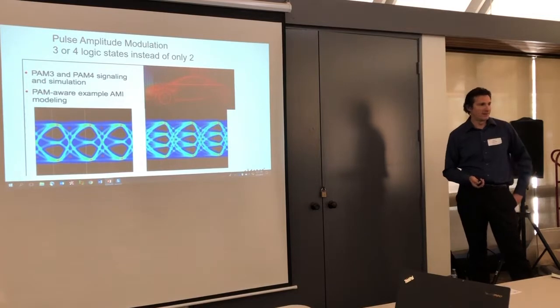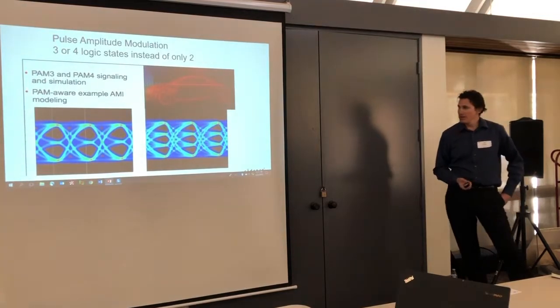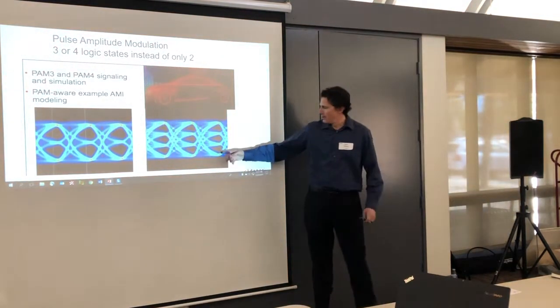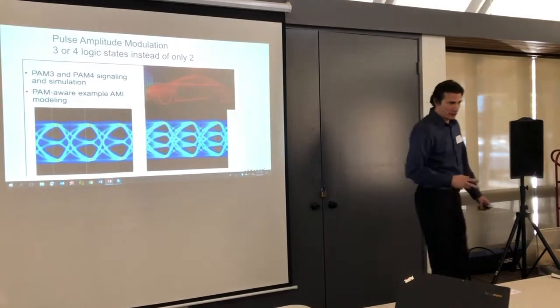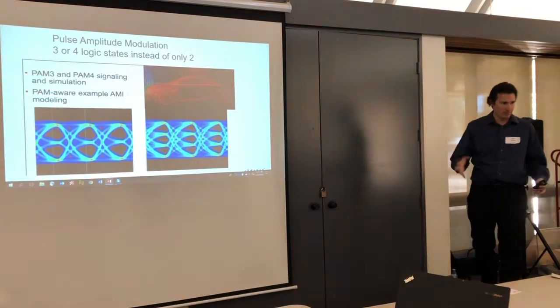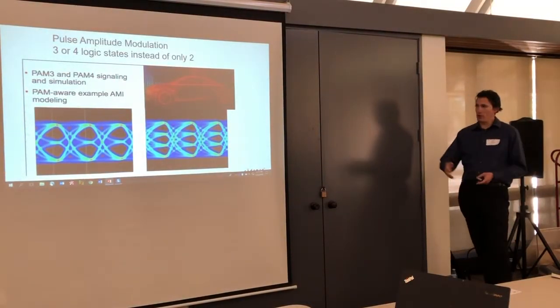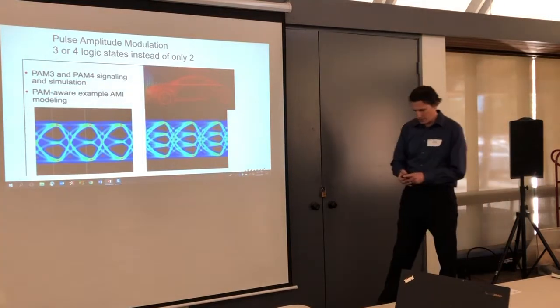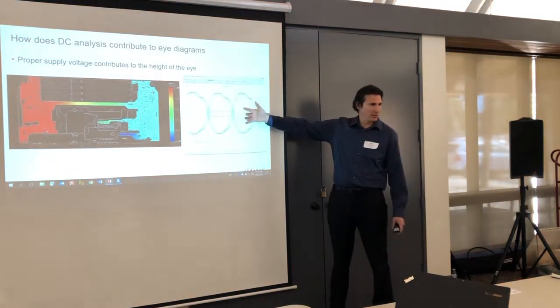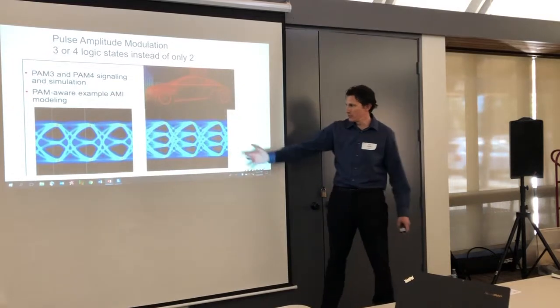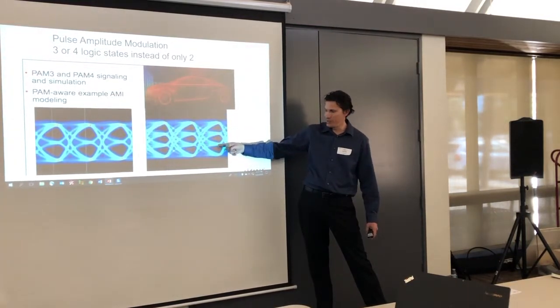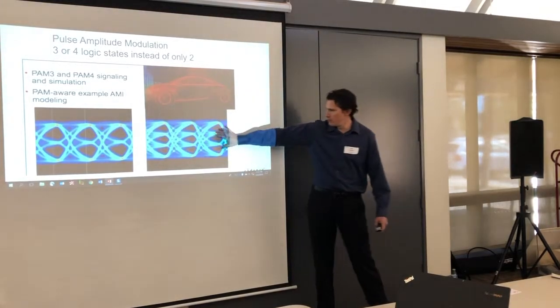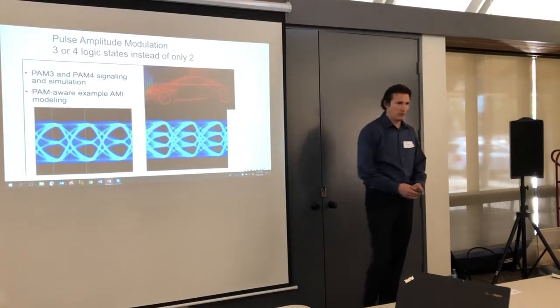So it's not using the 0 and the 1, it's using... Yeah, so you kind of got 4 different logic states: 00, 01, 10, 11. And so you can kind of think of it, you're shoving twice the amount of data down as what you had before. But also, imagine what you had to do to get this eye diagram clean. The signals have to be super pristine to clearly measure this versus that. Because if these two in the middle are kind of crossed over, then you've kind of lost the whole point of doing all of it.